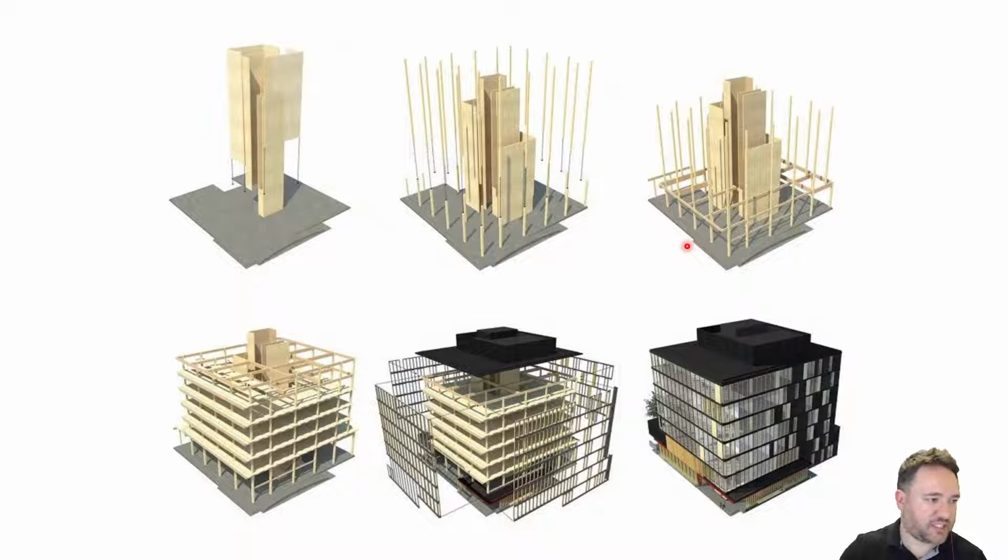This is what that building's construction looks like. So you can see the internal lateral force resisting system, which is the core and the elevators and everything, is made out of timber CLT. And then the outer structure, the gravity frame, is built out of timber beam columns, CLT slabs, including a wood envelope. So this is a very showcase project for wood construction in Canada.